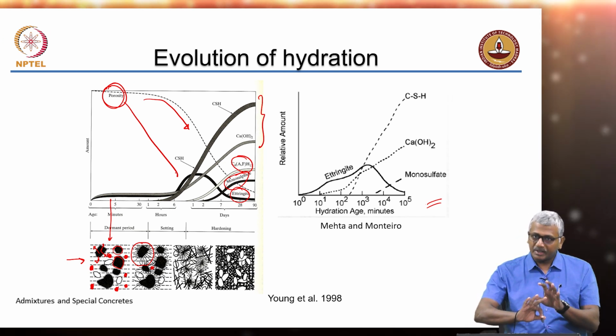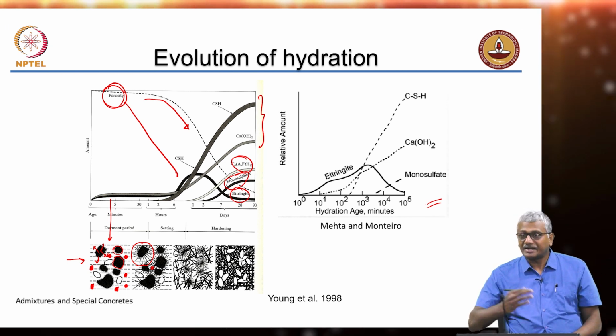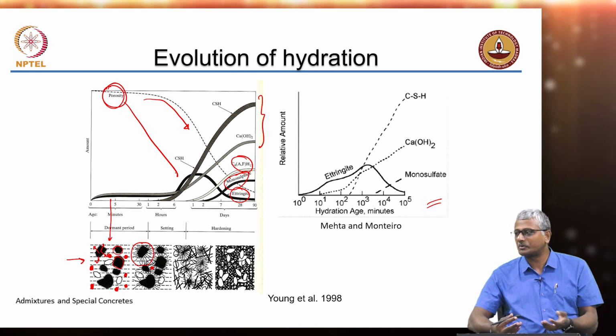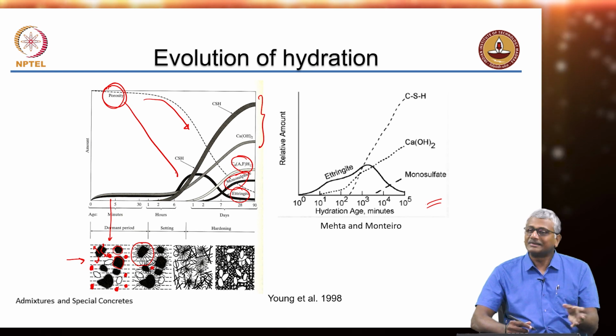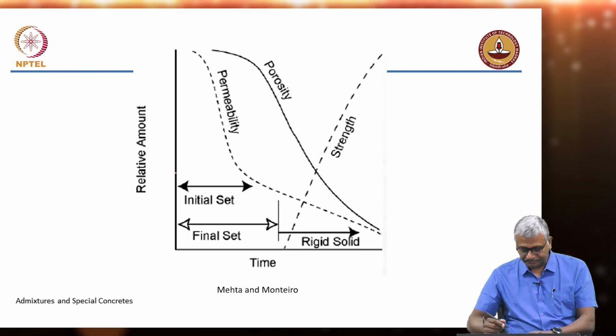Okay, so it's important to understand from the overall perspective. Now, that doesn't mean that we don't cure concrete with low water cement ratio, because hydration is only less. Why bother curing? It's not correct. There are other problems with it, which we'll talk about when we talk about high strength concrete.